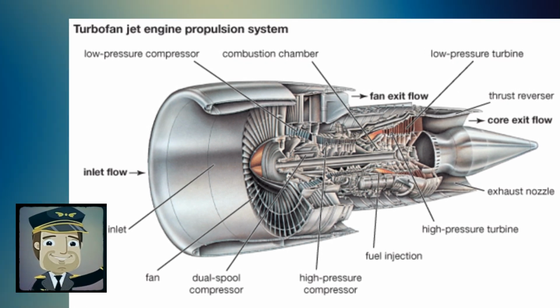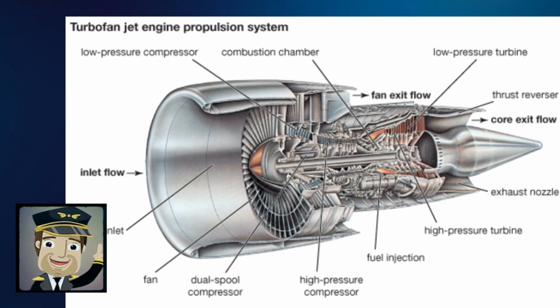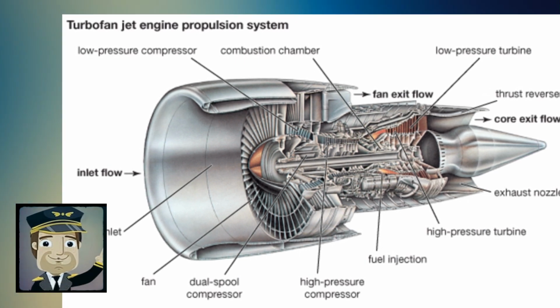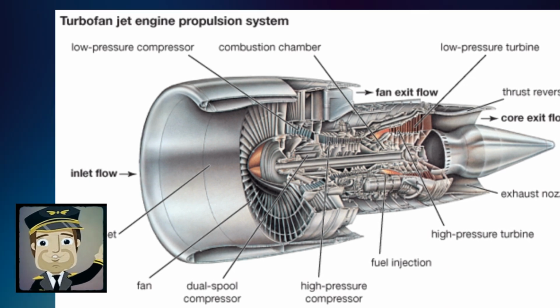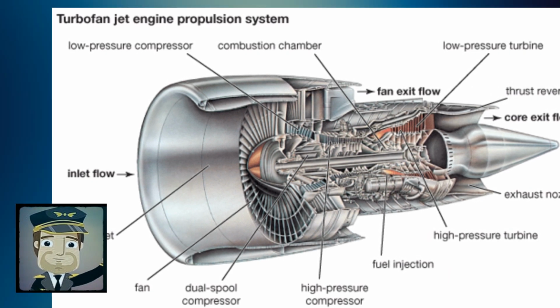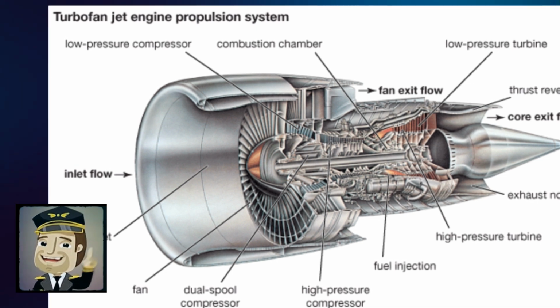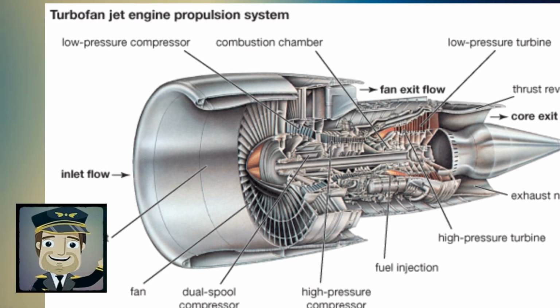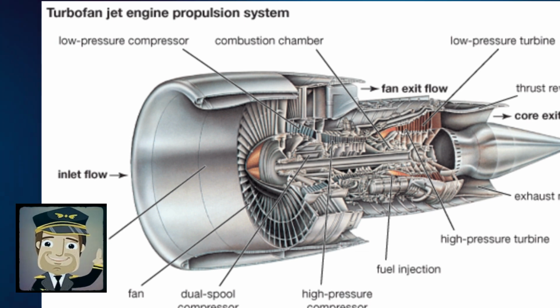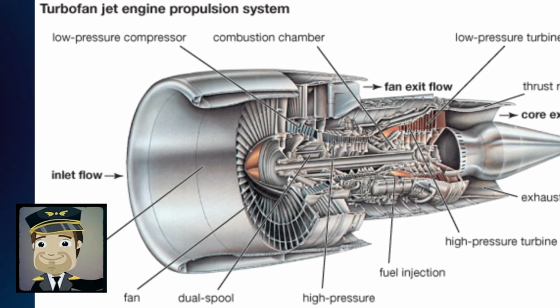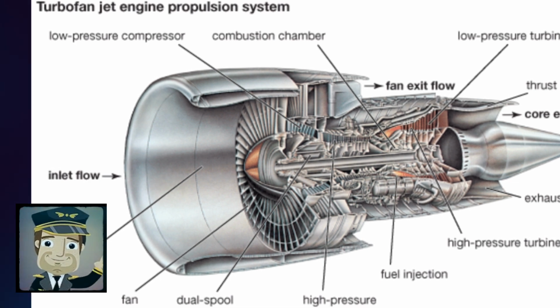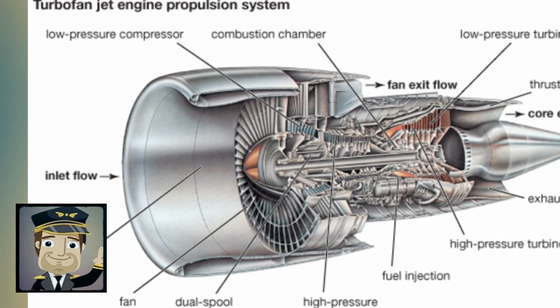Extracting shaft power and transferring it to a bypass stream introduces extra losses, which are more than made up by the improved propulsive efficiency. The turboprop at its best flight speed gives significant fuel savings over a turbojet, even though an extra turbine, a gearbox, and a propeller are added to the turbojet's low-loss propelling nozzle. The turbofan has additional losses from its greater number of compressor stages, blades, fan and bypass duct thrust.